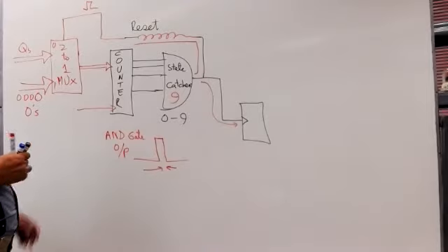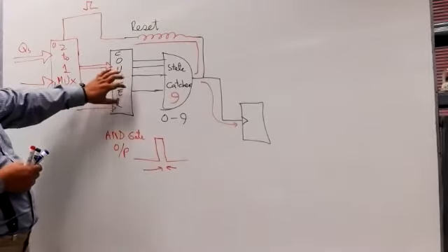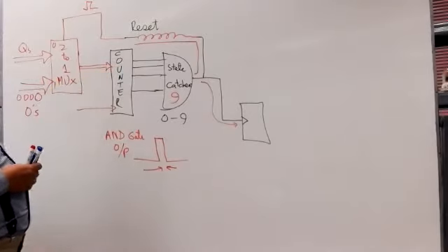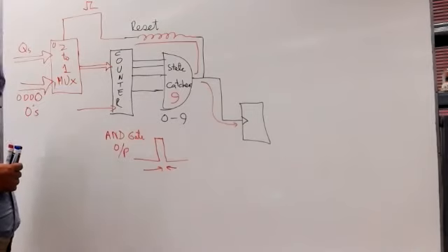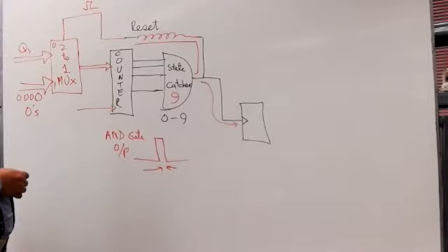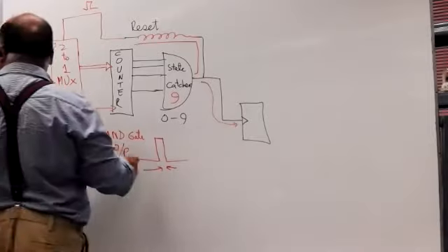So you will see that throughout computers, you never really reset anything. If you want to zero something, you load 0 into it. You don't reset. Direct inputs are never used in many circuits because they are asynchronous inputs, and people don't like things that don't happen at a clock edge.